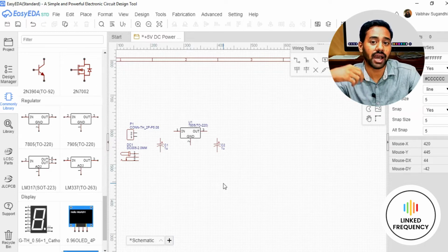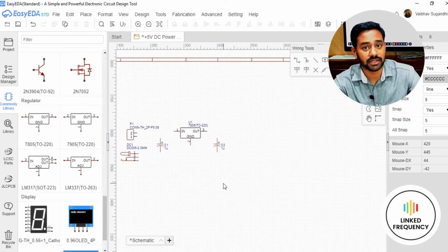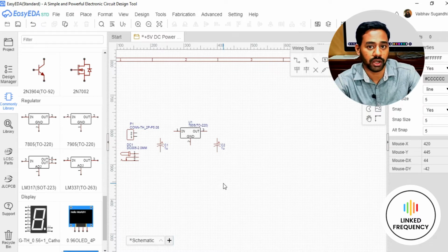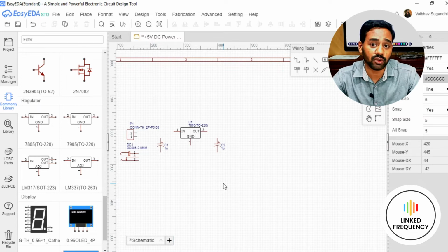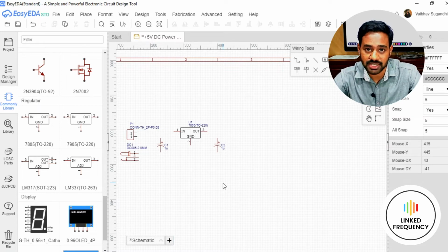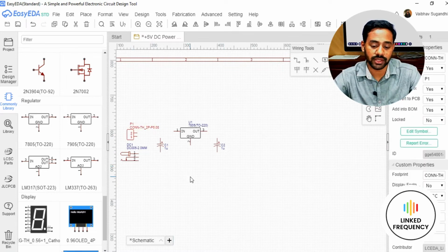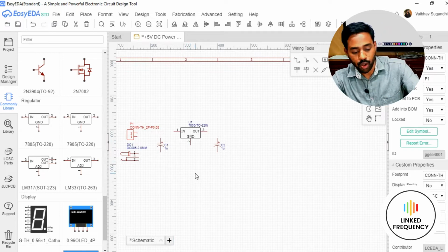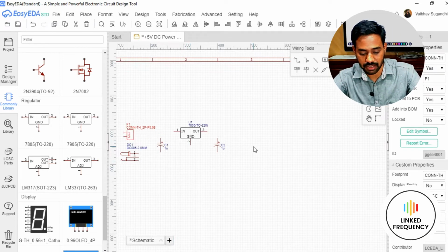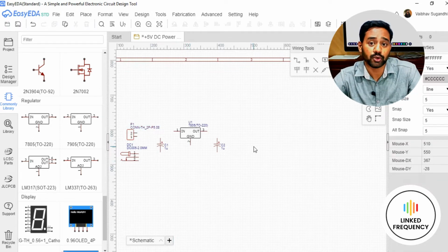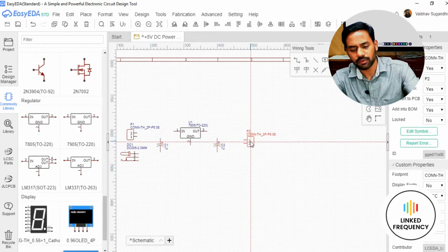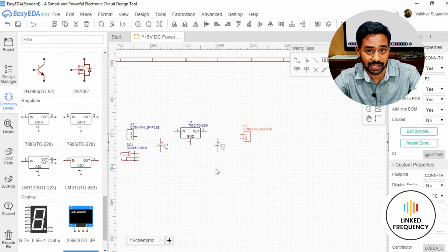Of course, we have another option right now. We can go with the RMC connector, we can go with the normal header connectors, or we can go with connectors of 5.08 pitch. Whichever is comfortable to you, you can go ahead with that. As per my industry experience, I believe that we need to go with a 2-pin header connector, or maybe a 2-pin connector, which is essential for your input and output as well. So it will look like a symmetric design, right?